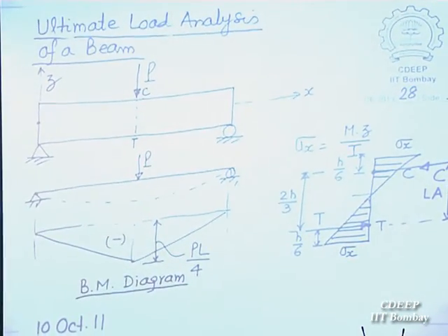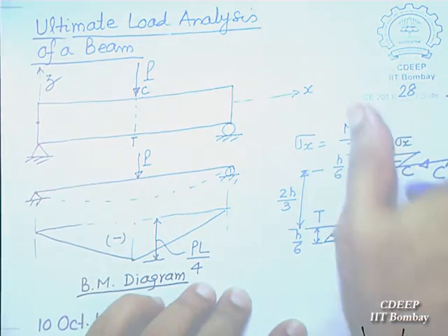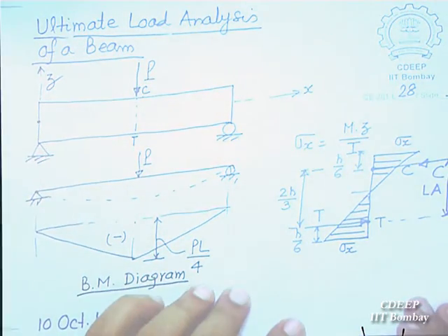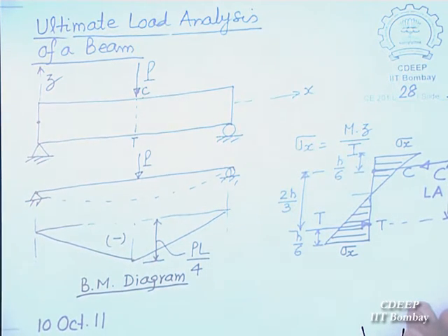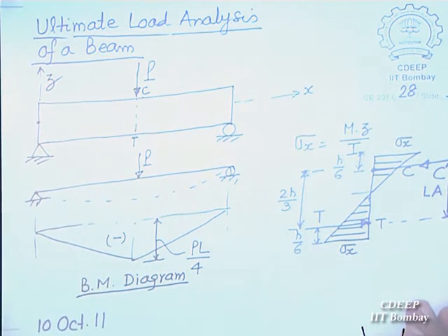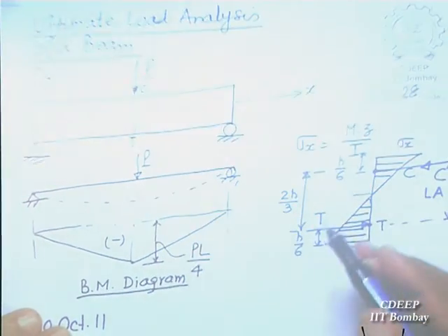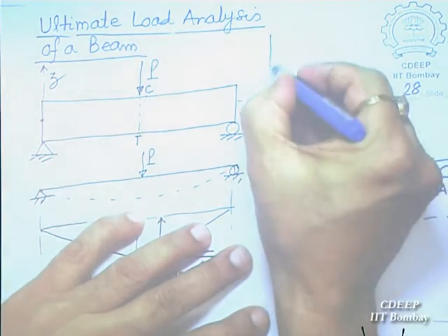And this lever arm is the one which produces the moment acting on the cross section. I mean, these are equal and opposite forces, one a compressive force, one a tensile force, and they will give you a moment, which is acting at that section. So you must realize, after all, where does moment come from? Moment comes from the stress distribution. Because of the stress distribution you have forces, and that must form a couple. So this is a couple which is formed. What I am trying to say is that yes, a time will come when this extreme fiber will reach, because you have this simple diagram.